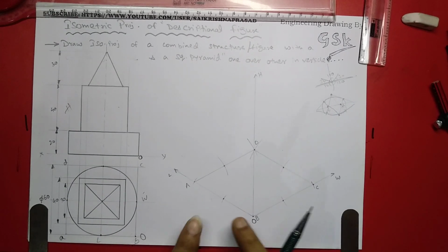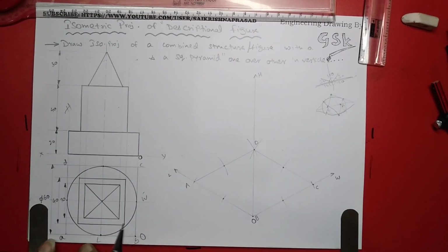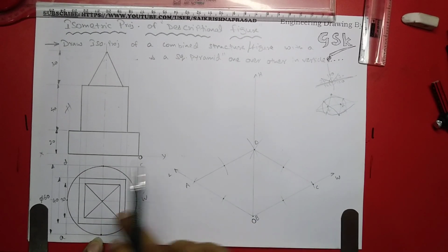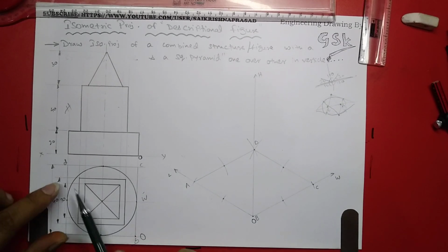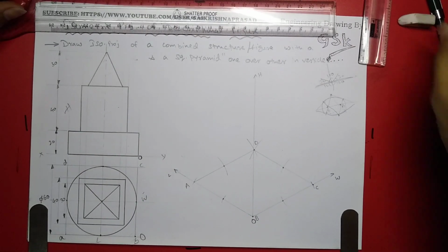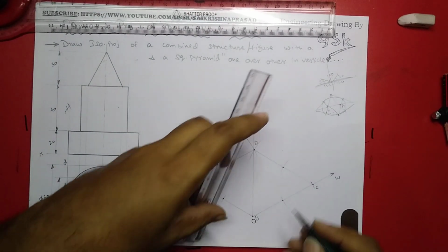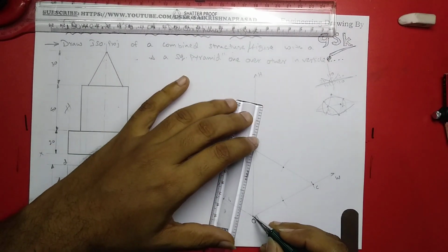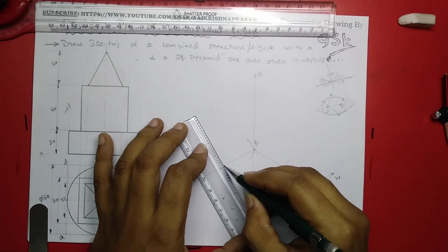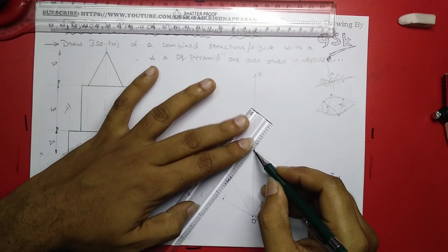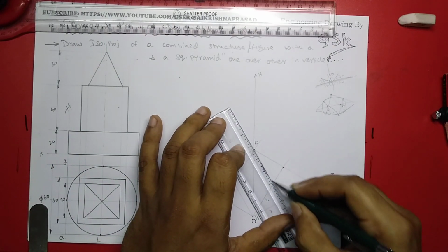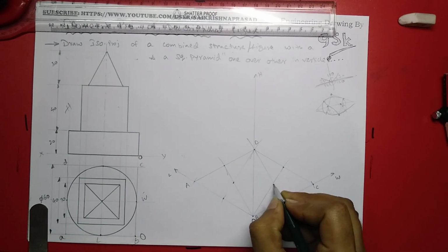So see here, this ABCD rhombus is a resemblance of this, right? Then this ellipse would be the resemblance of this circle. So here we can construct the circle by using this method. So already we got the midpoints. We have to join the lines to the opposite corners. So we got focus points over here.